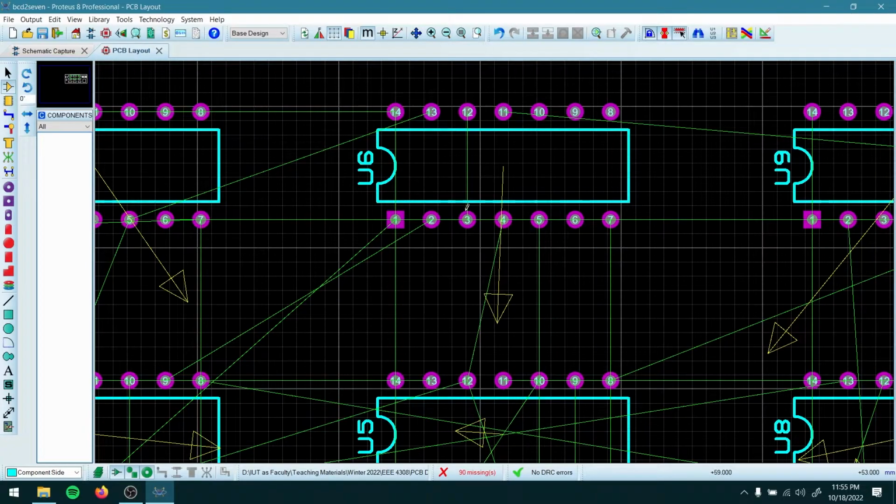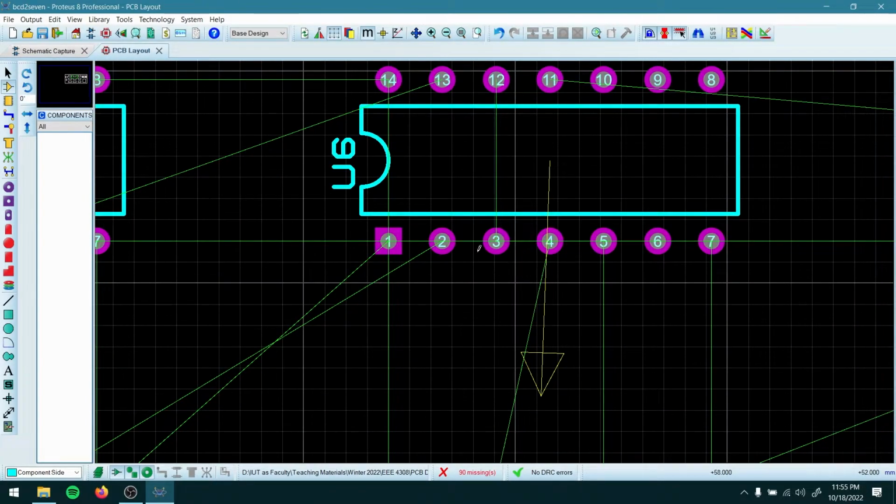These are the portion of the PCB which will connect the components with our PCB, right? But the size of these pads is very small, and in general in Bangladesh our technology is not that good. So whenever you use this kind of small pads, sometimes they get removed from the PCB. That's why we need to use larger pads, something like this.